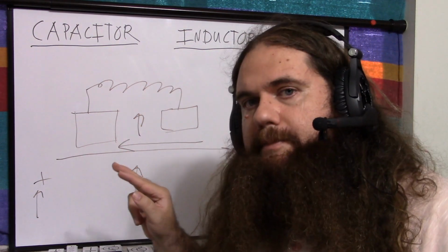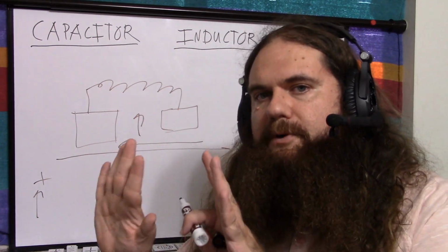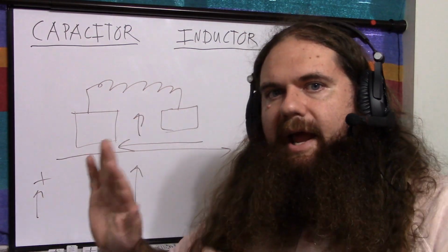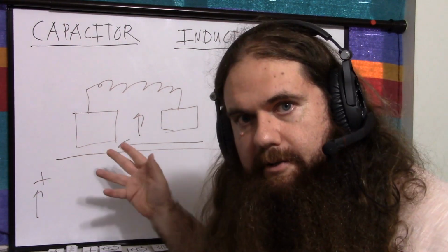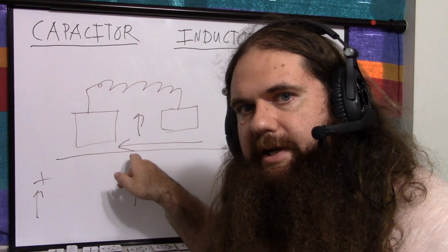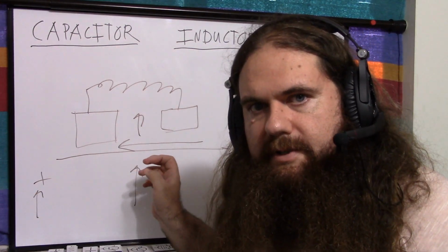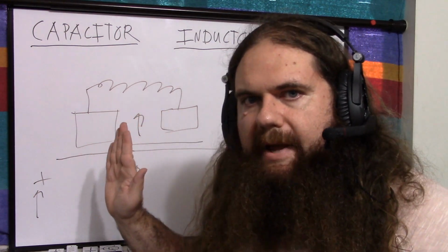So the current will go up, but it's still pushing. The voltage wants to make the current higher, so it keeps pushing and pushing and pushing, just like you pushing the wrecking ball. The magnetic field strengthens as the voltage is pushing harder than it needs to for the current. And as the field strengthens, this back EMF shrinks and shrinks until the voltage is successfully putting across the current it wants to put across, which matches the strength of the magnetic field, and there's no more back EMF.